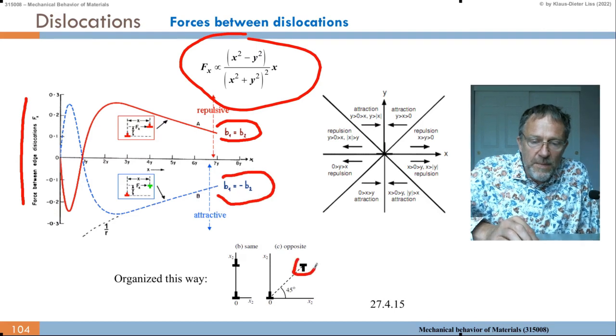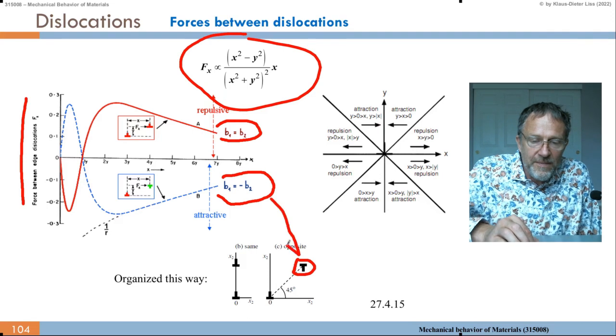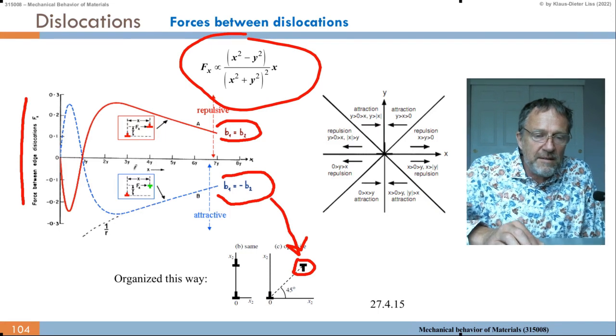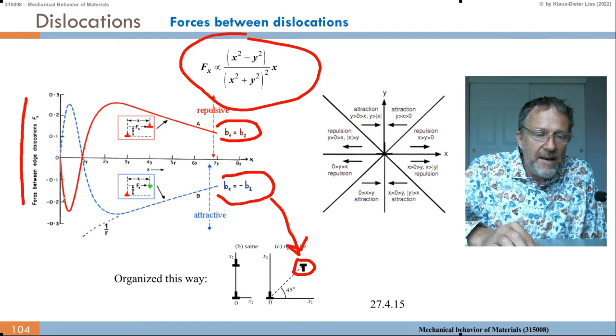So this is when you put the edge dislocation upside down. The second one is inserted from the bottom. If you insert the second from the bottom, basically the figure turns around in having this attractive, repulsive behavior, compared to B1 equals B2